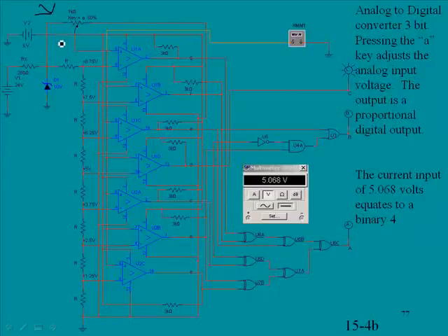Notice this is the voltage being applied as the analog value that we're evaluating, so you can set this to any of those analog values between 0 and 10, and you should be able to illuminate the light bulbs that are attached to the three logic levels indicating the 3 bits of our possible outputs.